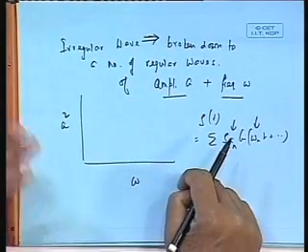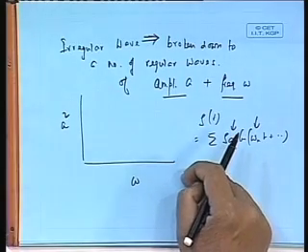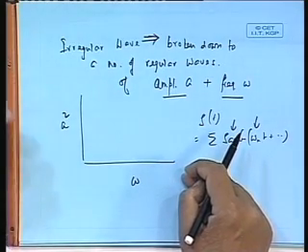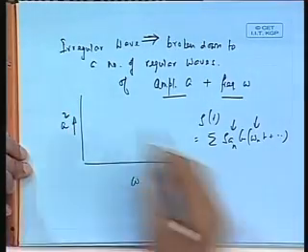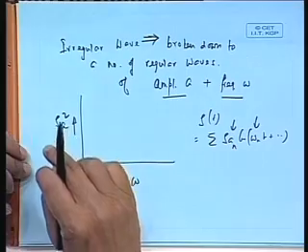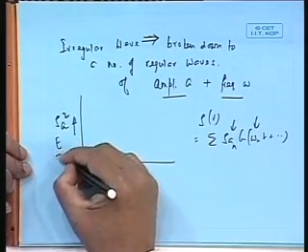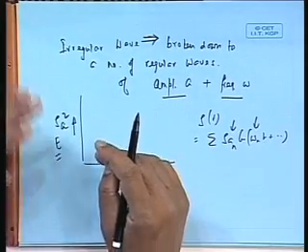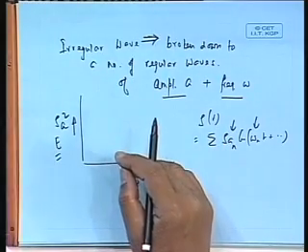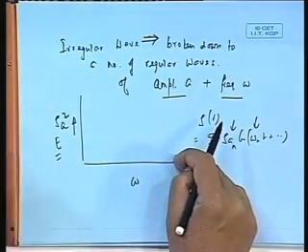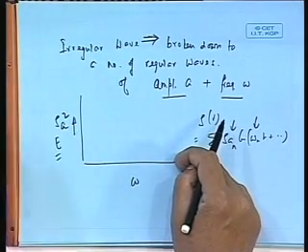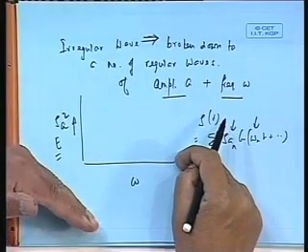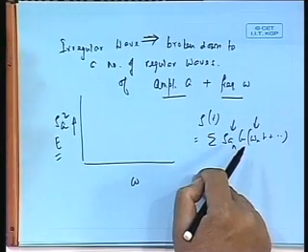Instead of that, the logic says that plot is less meaningful than plotting on this side something proportional to amplitude square, because that would be proportional to energy. Yes. So instead of plotting amplitude against frequency, that is the amplitude distribution against frequency, if you plot the square of amplitude distribution against frequency, you are actually plotting energy distribution against frequency, the energy of component waves.